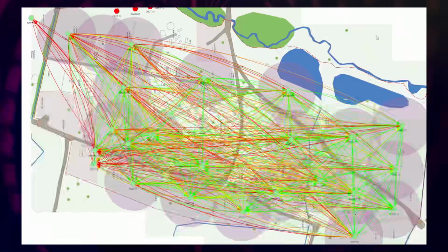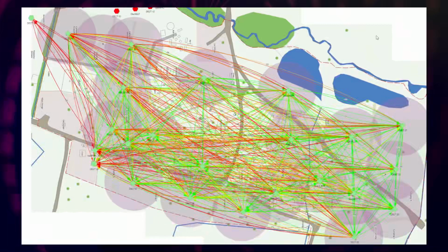This is one quite interesting little thing from the DECT network. The DECT base stations all need to synchronize with each other because it's a time division multiple access system, so all the base stations need to be on a synchronized clock. We don't have this on GSM, which is why we don't have handover right now. What the DECT system can do is synchronize over RF links between them.